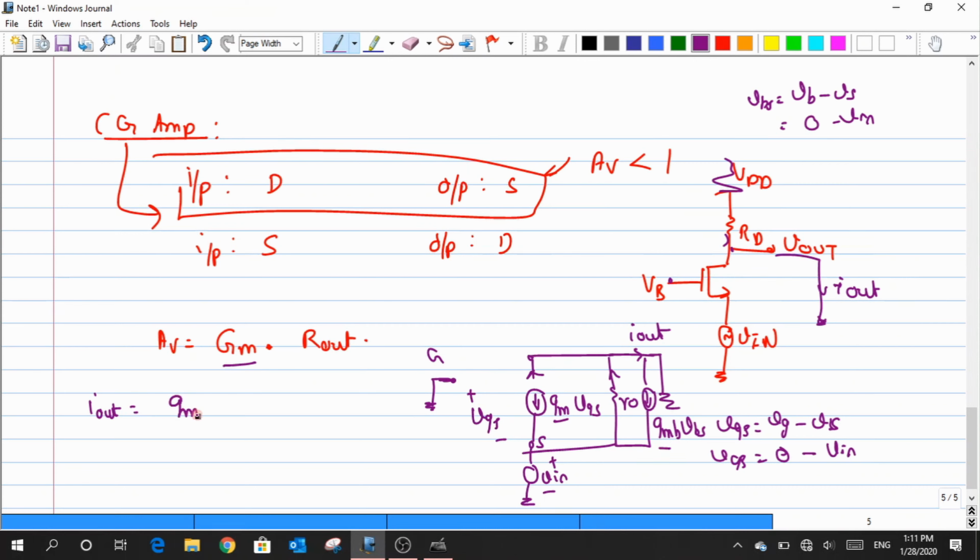So I would have something like GM prime Vn as one of the current components, or combining both the current components, and there is also a current that flows through this R naught. What is that current? That would be Vn by R naught. Having got this Vn at one end, I can pull out this Vn and divide in order to define my capital GM.